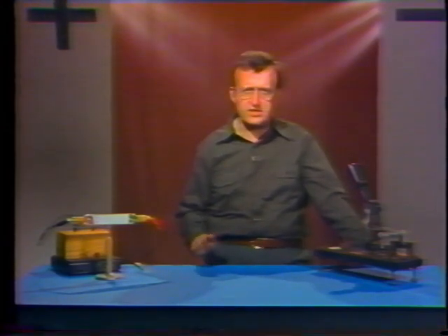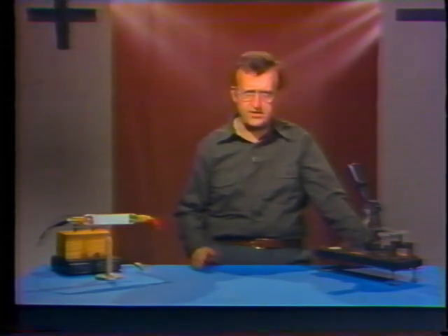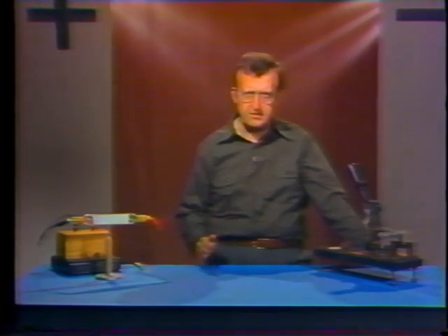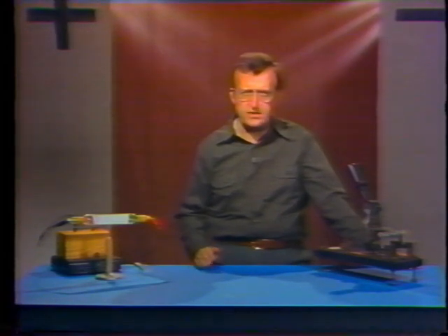Another advantage is that circuit breakers are better able to interrupt electrical arcs. As I mentioned earlier, an arc is the flow of current through air between 2 points. Air is normally a good insulator, but when it's heated, it can become a conductor. Arcs occur when a switch is opened to interrupt the flow of current through a circuit.